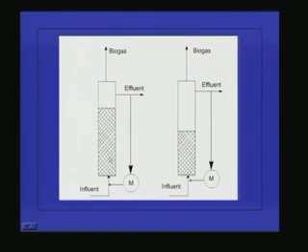That means one particle will not be in contact with the other particle, everything will be in a fluidized form. As a result of this fluidization, there will be very good contact between the microorganisms and the organic matter present in the wastewater. So the treatment efficiency will be very high, and the biogas produced will go from here and we can collect the treated effluent from here. Because the microbial growth is attached here, the effluent will be relatively clear, because not many microorganisms will come out along with the effluent.